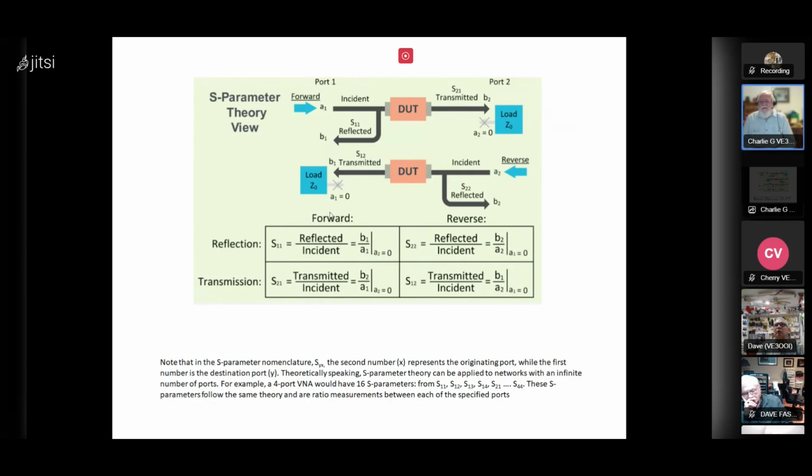Sorry, an S21 rather. S22 you can do, but not the S21 backwards. This is for an active device, so for an active device, you have to make sure the VNA can actually measure S22. Correct. Yes. Okay, fair enough. Thanks.